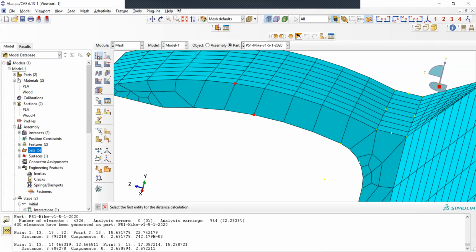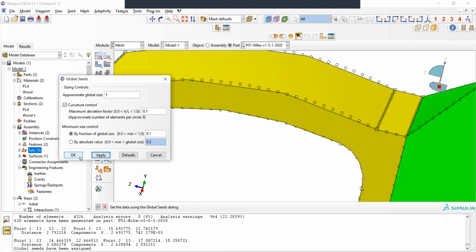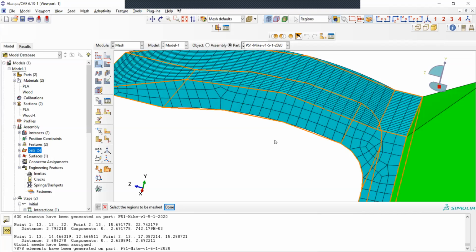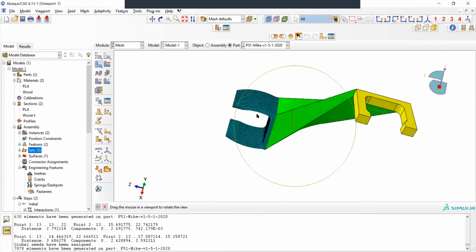And that means if I assign the general mesh size to 1/3 of that, so if it is 2.8 and I use 1, and now I remesh this area, now you have 3 elements per thickness. So this is actually the minimum, or at least the quantity of elements you should have, 3 per thickness. This is kind of like a rule to remember.